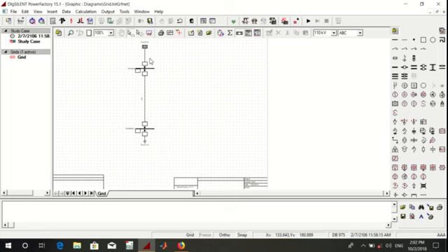Now define each new component that we have joined to our system. The first one, our grid. This is the source that is fed to bus bar number 1, and from bus bar number 1 to bus bar number 2. In connecting the transmission line, we should remember that we should select first that bus bar that the source is connected to. For example, I cannot connect the transmission line from 2 to 1. I should connect from 1 to 2, from bus number 1 to bus number 2.